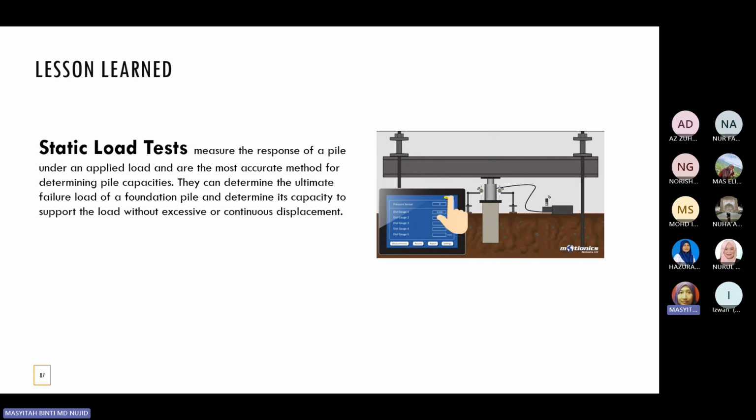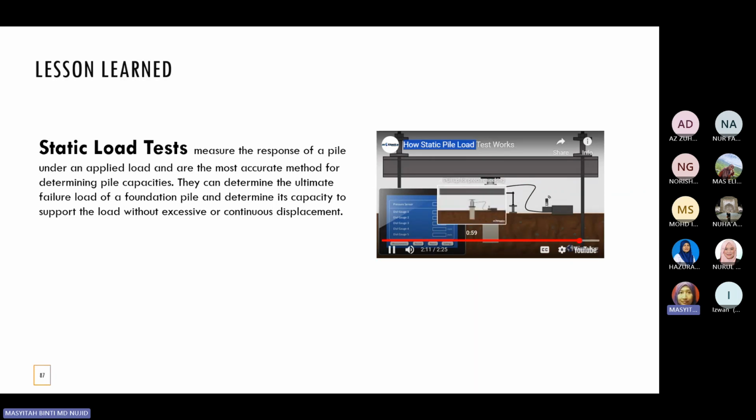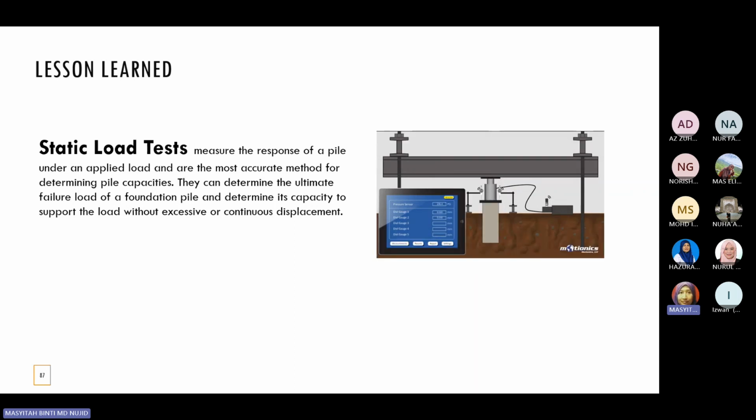Zero all readings in the app to start the test. Start the test by applying the load through hydraulic system based on the test standard procedure and let the app automatically record all devices' readings. Test results are seamlessly recorded and documented automatically. The same instruments can be used for axial tension and lateral load configurations. However, the test setup and loading structure would be different for each case.